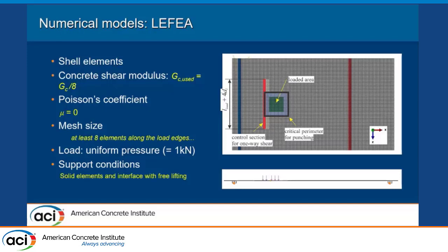The load was applied as a uniform pressure in the numerical models. In order to simulate the free lifting between the slabs and the supports, we created solid parts to represent the support plates, and we applied an interface with free lifting between the supports and the slab.